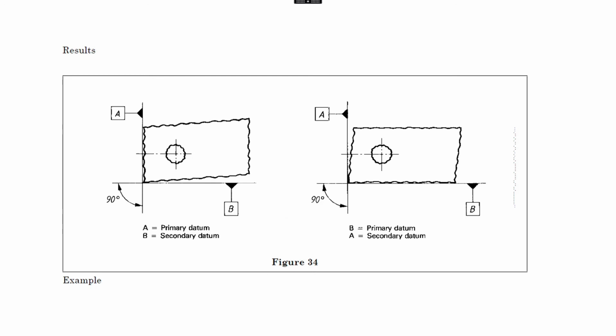A lot of manufacturers tend to split the difference, and what they actually do is put the hole in relative to this point here. So they half this error, but the reality is when you're using GD&T, the right way of doing it is to push the part up to where it stops, which would be this location here, and then you take the actual dimension from this location, not from this point here.